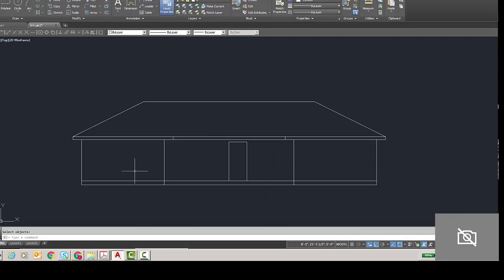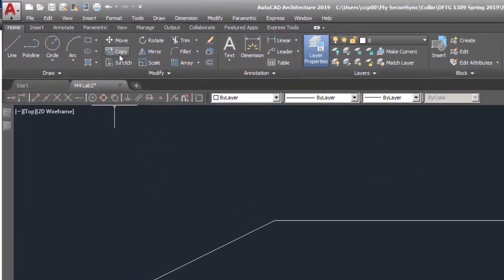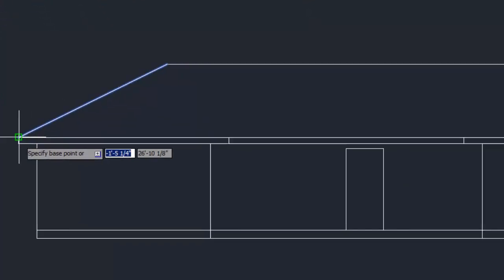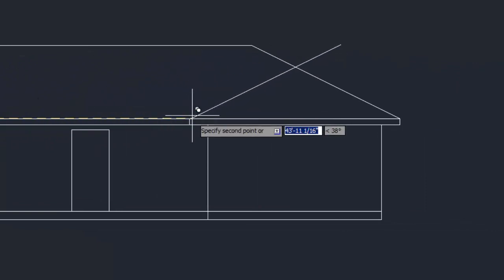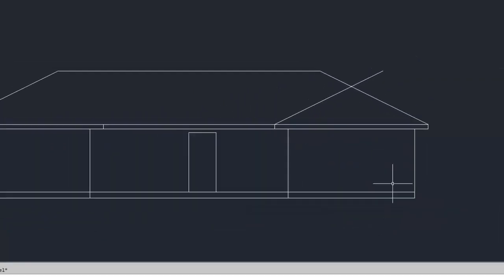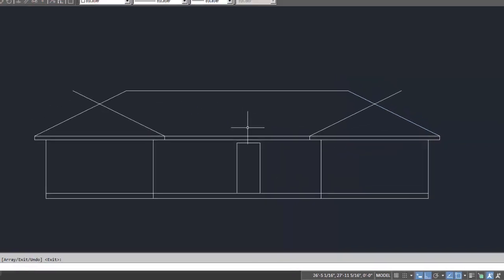So what I'm going to do next is to use those points and use these lines, these angles, and try to figure out what the easiest thing to do is, so I don't have to do any other commands. And I'm thinking what I'll probably do is go ahead and do the copy command. Use this as my base point, and I'm going to go all the way over to here to click that point. I'm going to go back into the copy command. This time I'm going to copy this line and hit enter. There's my base point, and then I go to that point.